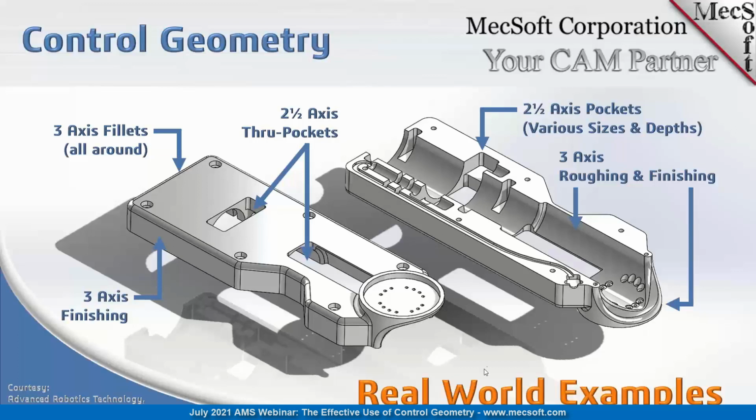Just that fillet. And this is a relatively complex fillet because it goes all the way around, but it also mates here at the front and then squeezes around on the backside. So we're going to look at that. And at the bottom, obviously, we have 2.5-axis pockets going on at different depths. And then we have some contoured surfaces that the user used 3-axis roughing and finishing pass there. And we're going to show you this part in a moment. Let's go to the next one.